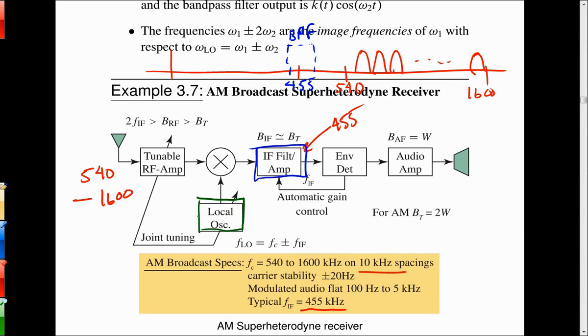So you might be thinking, why would you ever want to use the sum? That can be done. And in certain applications, you actually choose to move the frequency up higher rather than down lower. That could happen in a block converter operation, where you might want to move a band of frequencies just up to a higher frequency. So it'll typically move them lower? Typically move it lower, most receivers, because yeah, the difference is normally what you use.